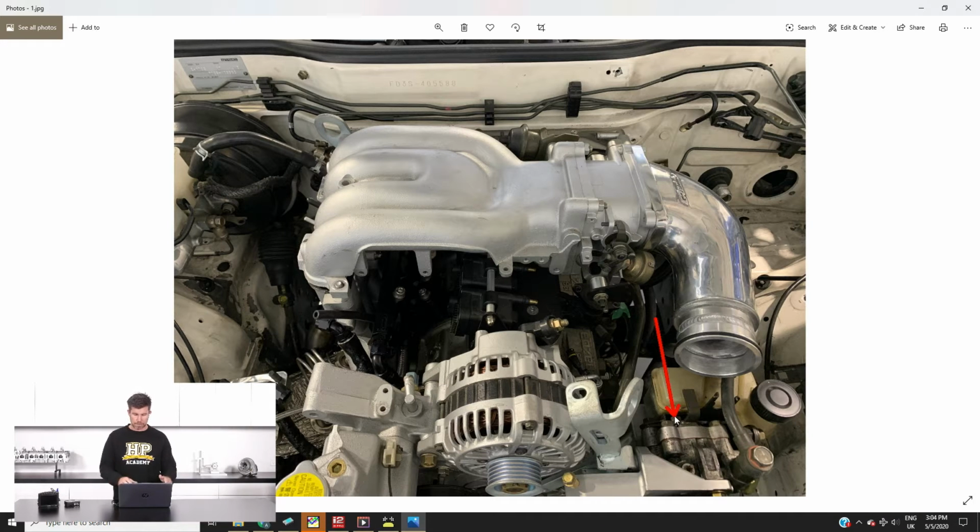We're obviously removing that because we don't have the aircon, so it actually gave quite a nice location for that big bulky drive-by-wire throttle motor. And while again we can't really see it, basically we could run a push rod directly from the drive-by-wire throttle motor up to the throttle body, so this all looked like it was actually going to work.